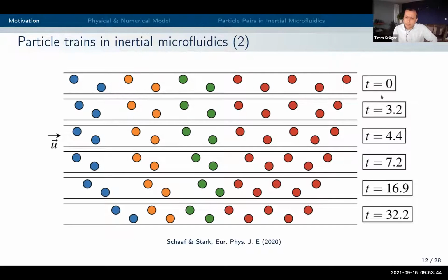Now, I'm not exactly sure how they non-dimensionalize time. I think they use a viscous time scale, but later on, I will show you some data where the time is non-dimensionalized in advection times, which basically tells you how many diameters you have to travel in order to see these effects. And that is extremely important for microfluidic applications, because if you have a channel that has to be, let's say, 10 centimeters long at a Reynolds number of 100, that is typically not feasible because you have huge pressure drops. I talked to experimentalists recently, and they said they have up to 200 bars at the inlet and atmospheric pressure at the outlet. So essentially what happens is that at some point you delaminate your chips and you cannot do it.